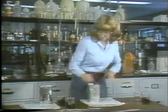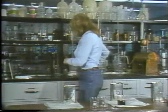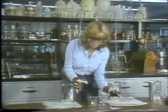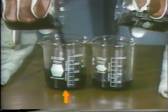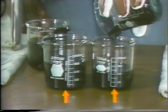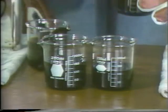Another factor that has a great effect on viscosity is temperature. To illustrate this point, we'll perform another experiment using two samples of the same lubricant. One sample has been carefully heated, while the other sample remained at room temperature. As you can see, when the lubricants are poured, the sample on the left, which has been heated, flows more rapidly from the beaker. Its viscosity has been lowered by increasing its temperature. However, the same lubricant at room temperature has a higher viscosity. It is thicker and flows from the beaker at a slower rate. As a rule, higher temperatures cause viscosity to decrease, while lower temperatures increase viscosity.